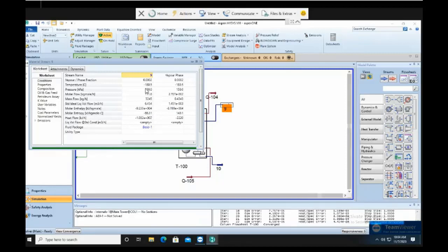The compound will deteriorate, no, what do you call it, it will break. A compound consists of molecular structure, so the molecule will break. It will decompose. That's the word. It will decompose and get damaged. So we don't want that to happen. So when the temperature at the reboiler is too high because the pressure is too high, then you need to lower the boiling point of the component at the reboiler.